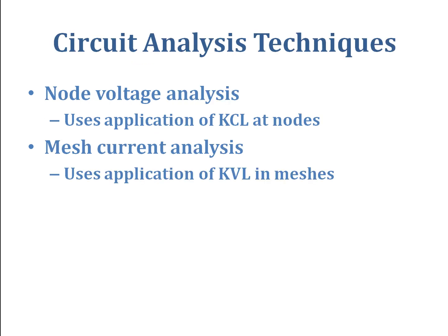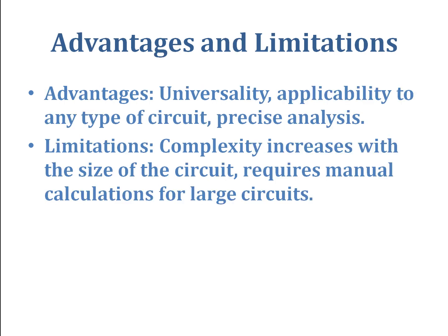There are two very important techniques that are used for circuit analysis. They are node voltage analysis, for which the law used is Kirchhoff's current law, and the second technique is mesh current analysis, which uses Kirchhoff's voltage law. The advantages are they are simple, universally used and applicable to any type of network. They produce precise results, and the limitations are that the complexity will increase as we move to larger circuits, and therefore manual calculation requires a lot of time.